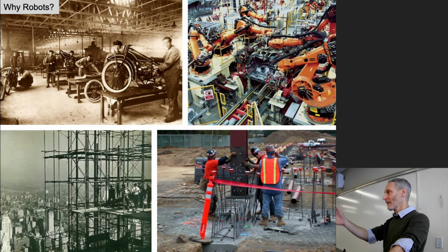Is that it? Well, it depends on what method of vision you're using. If you're using a LiDAR that's not that precise, it might try to do object detection and object avoidance by stopping when there's actually nothing there, or something really small that it detects as a point, and it stops itself. Could be, right? So you get false positives. It thinks it sees obstacles in its path and it stops, and you just can't get this machine to actually do things. It's just paranoid all the time. It's frozen with anxiety. I can't find or do what you're asking me to do. Again, a bummer, but not that big a problem in the grand scheme of things.